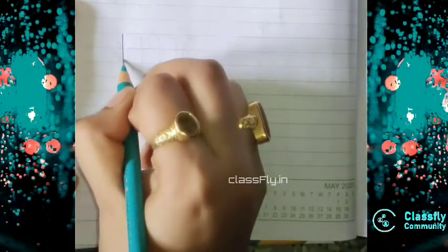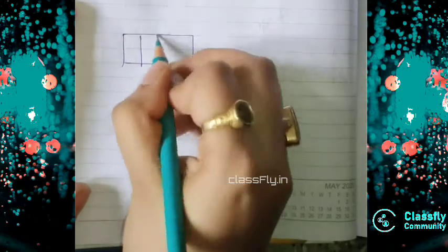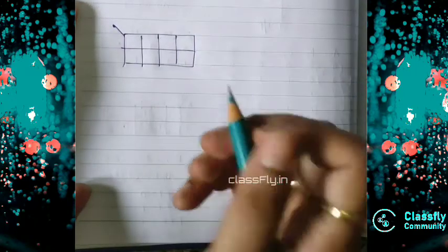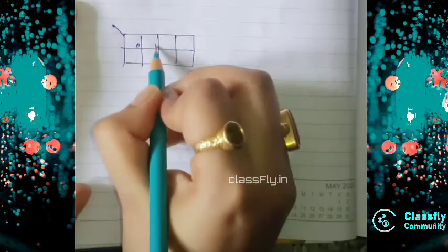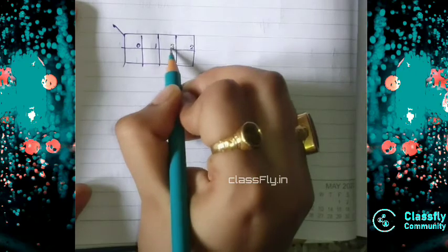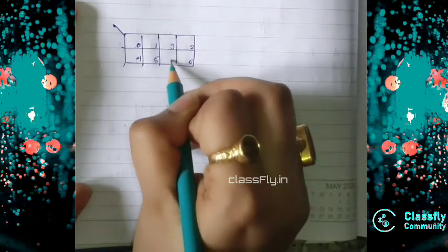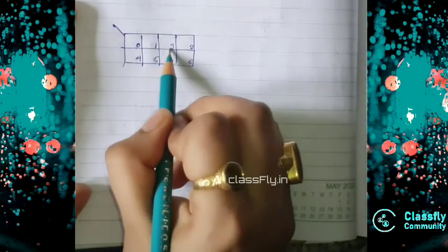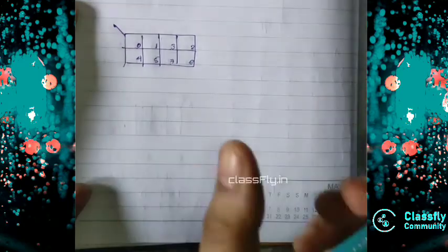See, for the sum K map, let's solve this. First make 8 boxes. These are the 8 boxes you made. And now start numbering. So you will number from 0. So 0, 1. After 0, 1, jump to the last, 2. Then again come back to this, so this 3. Then again 4, 5. Again jump and then come back. So what we are doing? 0, 1, jump, jump back 3, 4, 5, jump, back 7. We are doing this one.